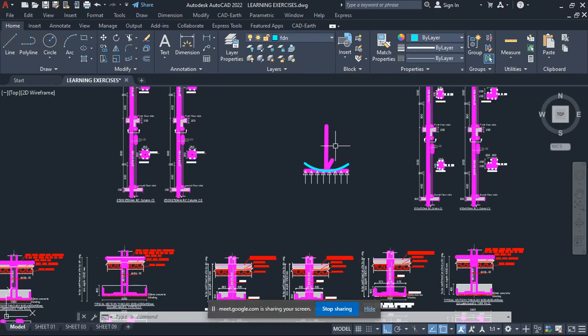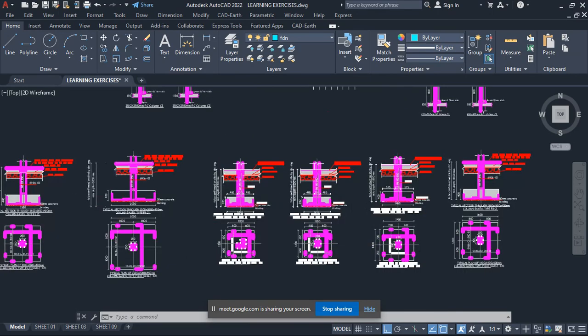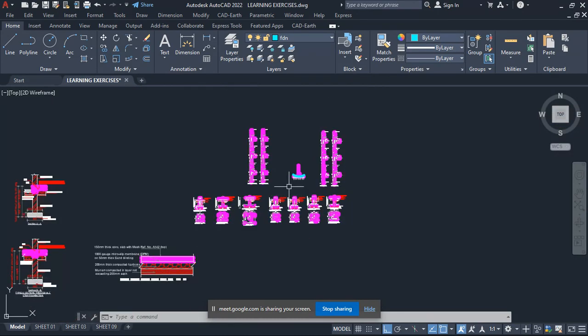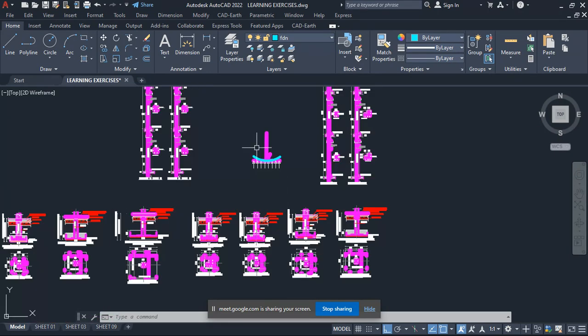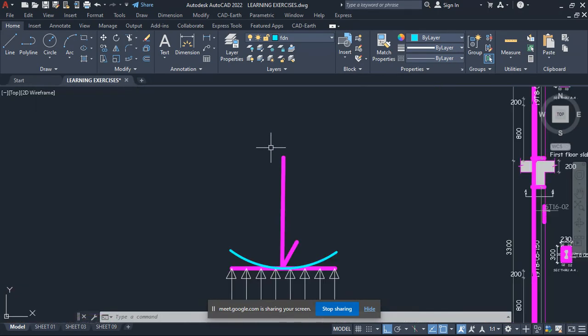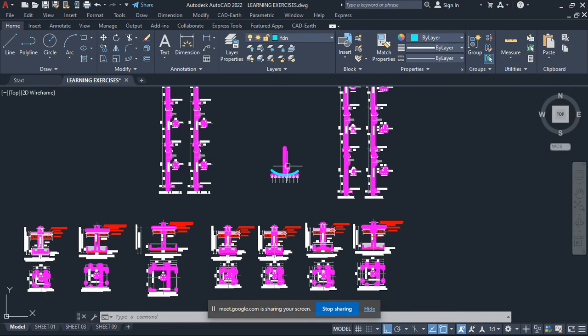So as you're opening, I will be just taking you through. The same applies with the base. You have to assume a size, then you check. According to axial load, we shall start with a size of 1.2 by 1.2 by 350. Then we apply the loads which came from the column and the moments. Then we check. If it doesn't pass, we increase the size as we are checking punching shear and bending capacity.